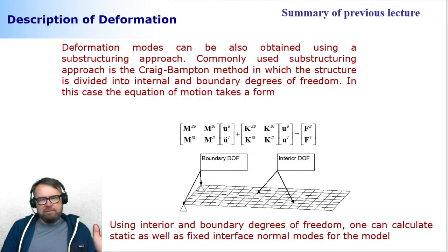The problem with eigenvalue analysis is that you have to set your reference condition, that is, how you're describing your motion in multi-body system dynamics, in such a way that there is no boundary condition in your finite element model.